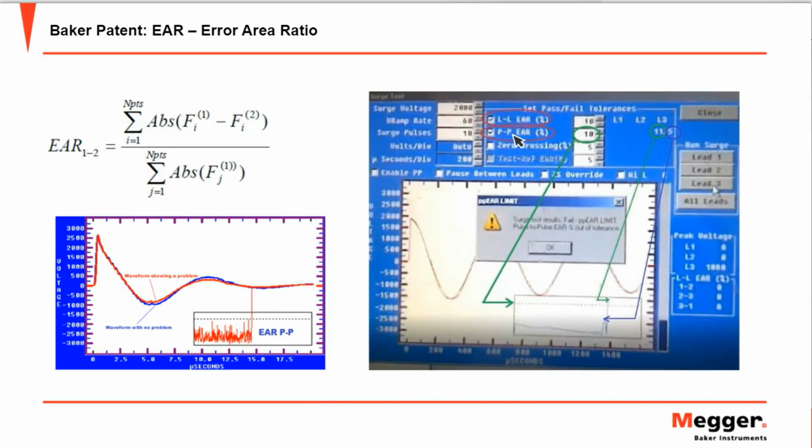I'm pointing here, the pulse to pulse. What is the pulse to pulse? So modern testers, we are applying current through, let's say, lead number 1 of the motor, having leads number 2 and 3 grounded. So lead number 1 of the motor is receiving the current, so we will have the voltage drop through the circuit, and we are increasing the voltage, for example, from 1000 to 1050.